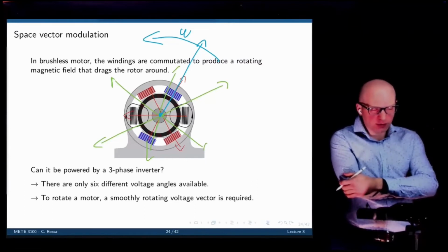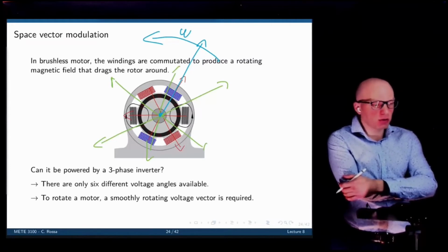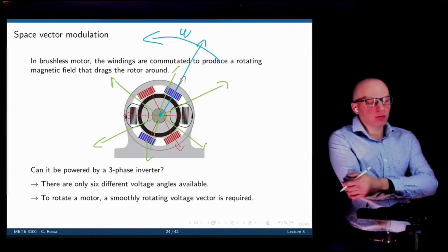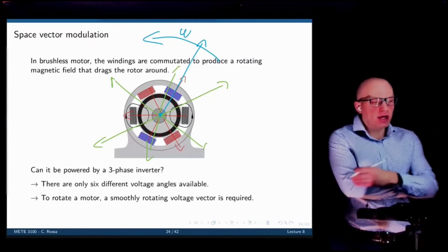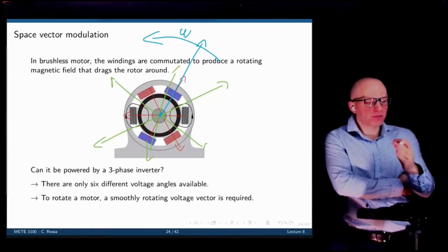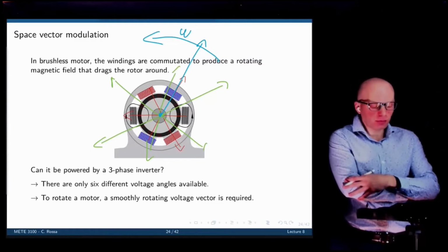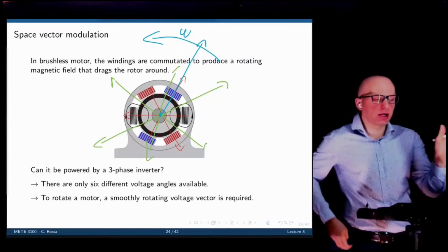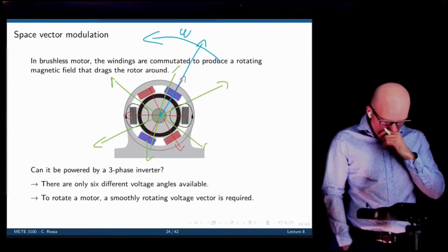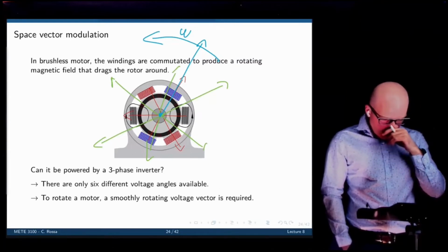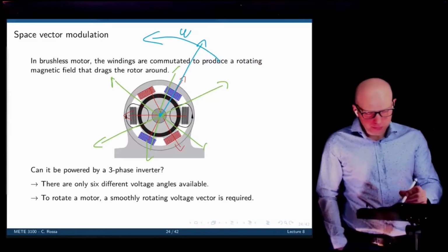That's the idea of space vector modulation. It's an idea to now define the duty cycle of each coil to control the voltage better, the average voltage better, to get this resulting vector moving in a specific direction in time, and then drag that around so that it can move the rotor at a specific speed. That way we ensure a smooth rotation in the motor.